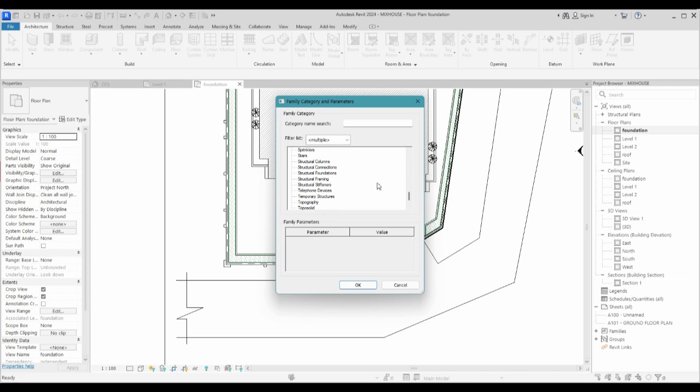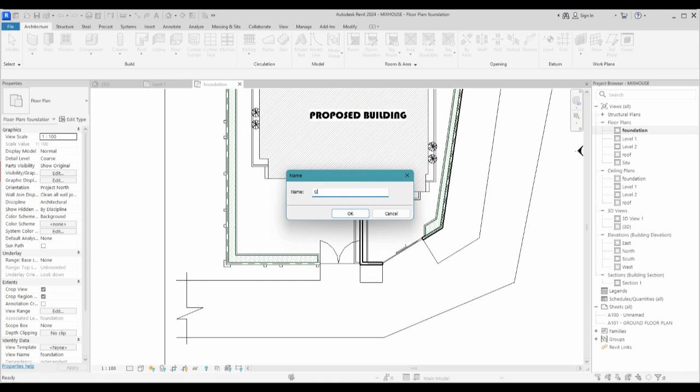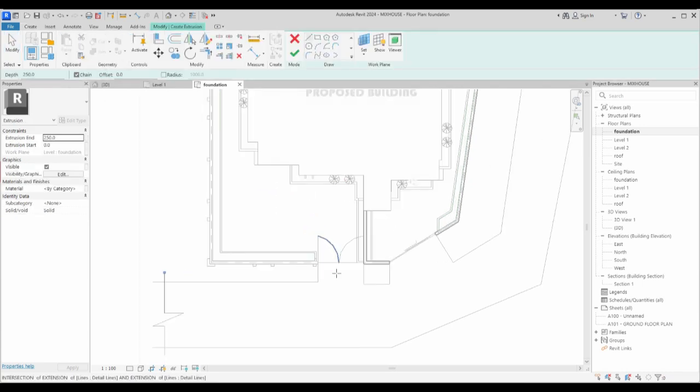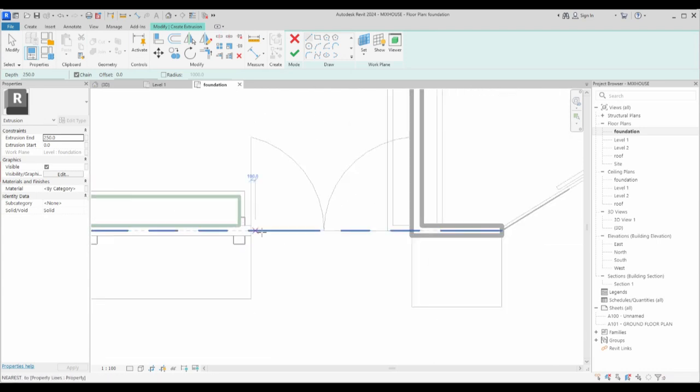So when you see something different from the 3D that I put on the page, most especially, it's not too different. So what we do now is that you click on this and create your own gate. If you have gate here, fine; if not, then click on generic model and click on this and say gate design. So you start from there. When you click on gate design, you can use any of these types, whatever you want to do. But what I want to use most is extrusion. I start with it. So I'm going to combine two or three things together here that will give me my idea of what I want to do.